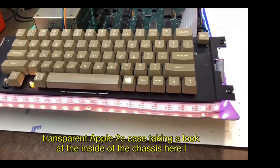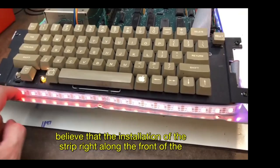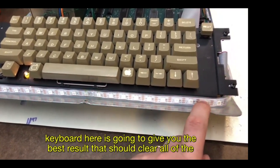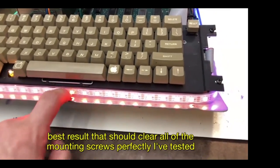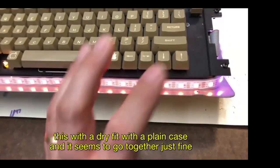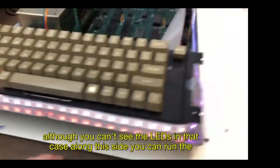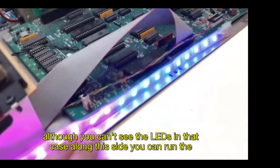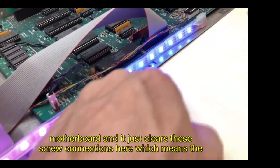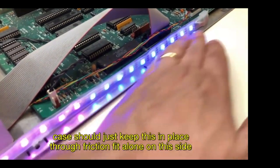Taking a look at the inside of the chassis here, I believe that installation of the strip right along the front of the keyboard here is going to give you the best result. It should clear all of the mounting screws perfectly. I've tested this with a dry fit with a plain case, and it seems to go together just fine, although you can't see the LEDs in that case. Along this side, you can run the strip right up along the edge of the motherboard, and it just clears these screw connections here, which means the case should just keep this in place through friction fit alone.